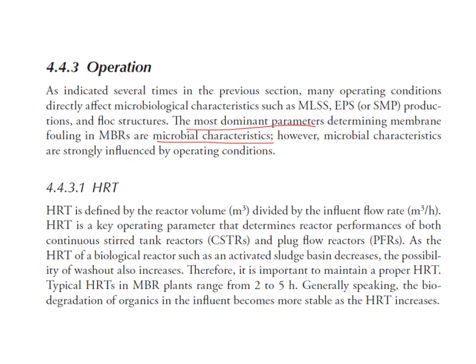However, microbial characteristics are strongly influenced by operating conditions, so that's why we have to look at these operating conditions. One of the typical operating conditions in an MBR system is, of course, the HRT. HRT is defined by the reactor volume divided by the influent flow rate, and this is a key parameter determining the reactor performance.